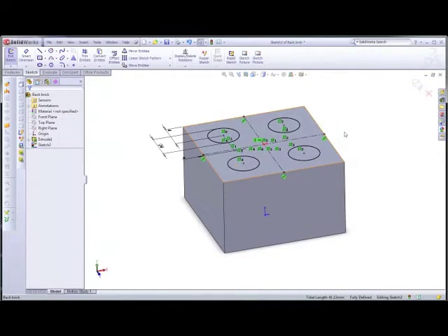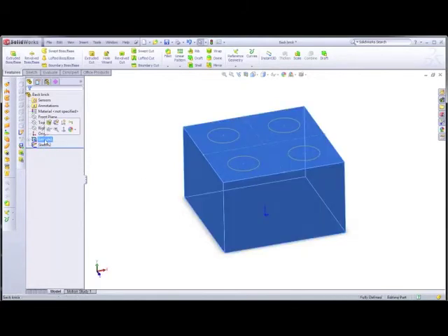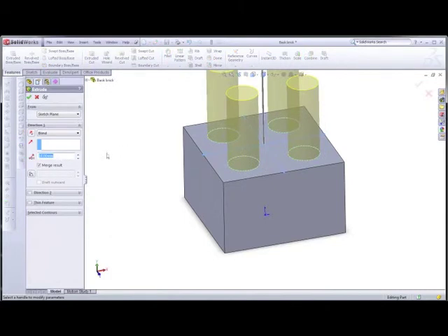Okay, so once we've done that, we can exit out the sketch and look down here. Our sketch has been created just below our extrude. So we go to that. If you highlight that before and then we click on extrude, it'll automatically select that as our item that we want to extrude. Right, in our extrude, we've got our options for how high we want it to be extruded,